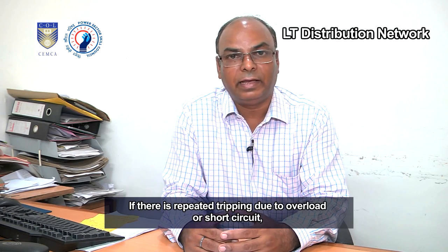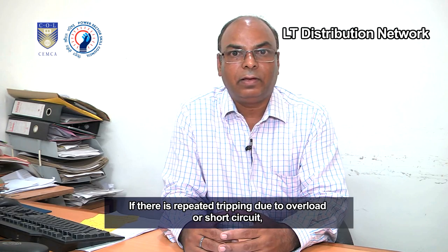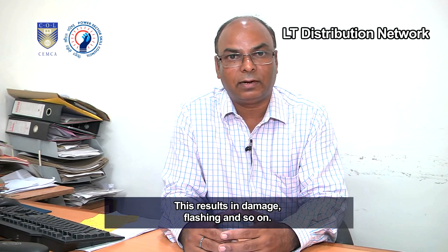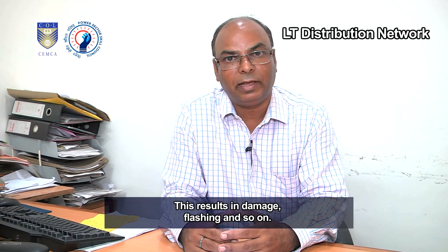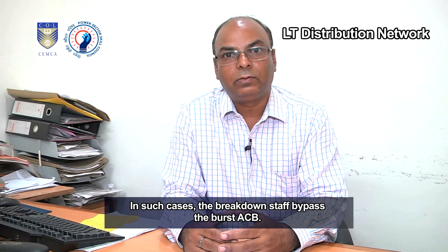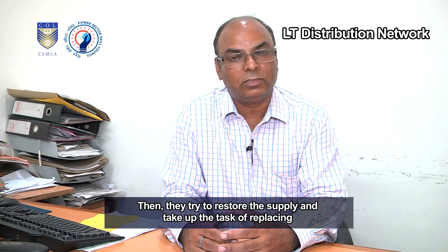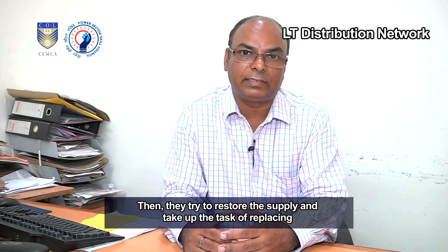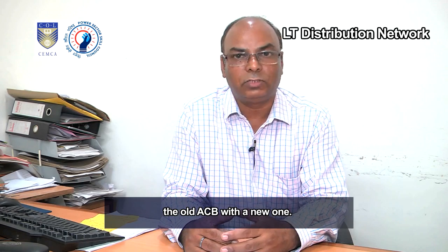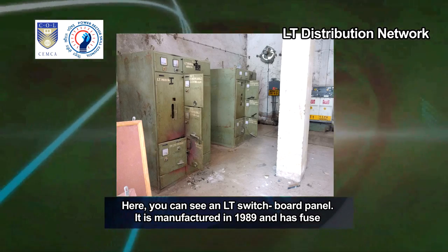made normal. If there is repeated tripping due to overload or short circuit, the ACB functioning becomes weak. This results in damage, flashing, and so on. In such cases, the breakdown staff bypass the burst ACB. Then, they try to restore the supply and take up the task of replacing the old ACB with a new one. Here, you can see an LT switchboard panel.